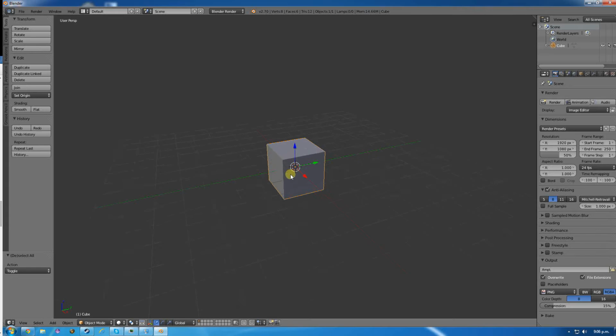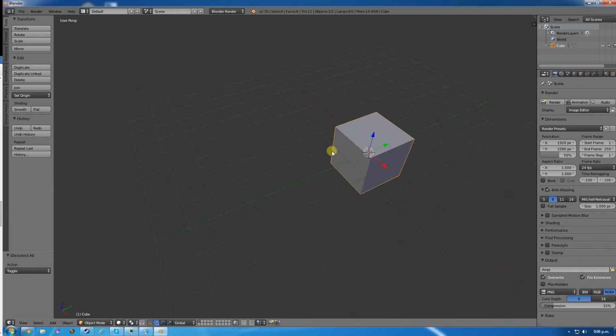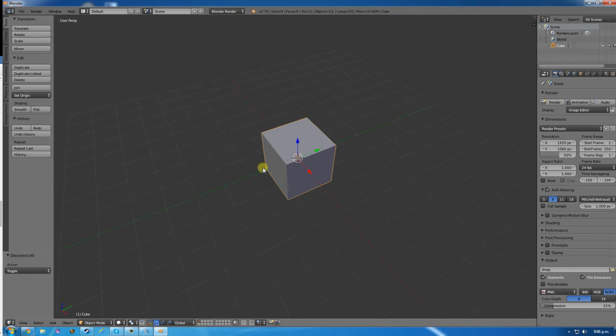And we've got the middle mouse button or the scroll wheel, scroll in and out. Middle mouse button click and rotate. So hold it to rotate. And then shift, middle mouse button will drag. Now it's important that you push it in that order. If you push middle mouse button and then shift, it still rotates. So it's shift and then middle mouse button, that will pan it.